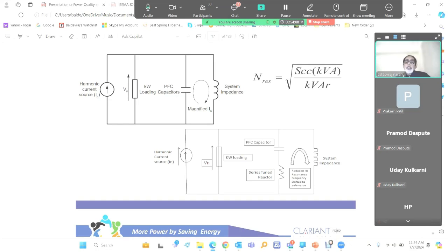And so it is doing all these jobs, avoiding the resonance, filtering some of the harmonics, and also reducing the inrush current. So this reactor is very, very crucial. So today, no capacitors are used without reactors because all the systems have harmonics. Everywhere there is a risk. So we have to mitigate that risk and we have to use capacitors with the reactors. And plain capacitors are almost prohibited today.